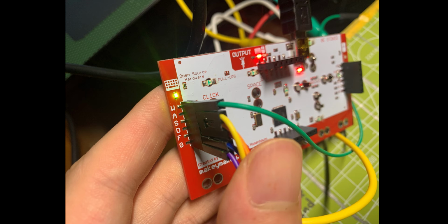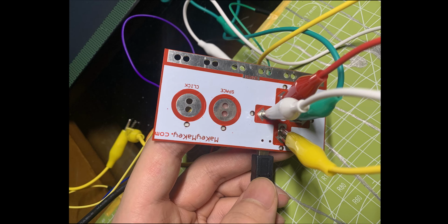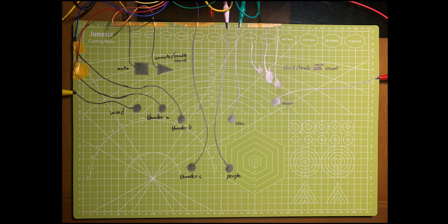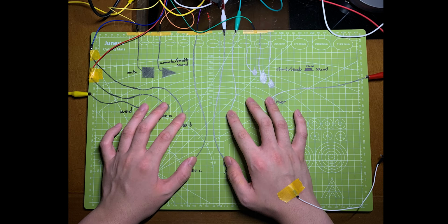There are 10 inputs on Makey Makey being used for this interface, 6 on the back and 4 arrow keys at the front. These inputs are connected with 10 conductive pencil-drawn buttons on the board, which include all the 8 environmental sound channels of the interface, and a mute and unmute button, in an attempt to make the button setup comfortable for the user to press on. The user's hand will be connected to the ears of Makey Makey using a conductive wire, so when the fingertips touch the button, a circuit loop will be completed.